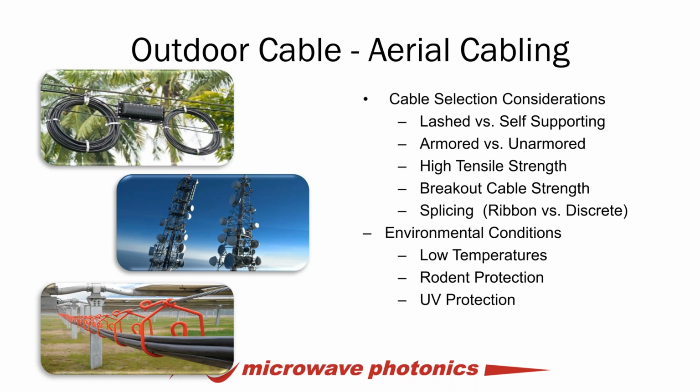What's the breakout cable strength? Does it need to be a high tensile strength cable? Should it be armored versus unarmored? Is it going to be lashed, or does it need to be self-supporting? What type of UV protection do you need? If you have a cable that's going to be in the desert versus in an Arctic region, those are two very different fiber cables, and the market has many selections to support that. Rodent protection: many times I've seen in the cable television business, the squirrels sure do like to chew through the cable.